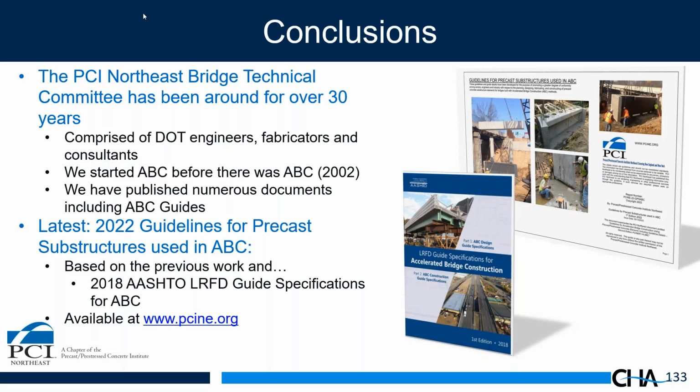Now, granted, this document was put together in 2018. There was limited research on seismic connections, but there was some research. So there are a handful of connections that are included that are seismic connections. The key thing is grouted couplers are difficult, especially when you're using displacement-based seismic design, because the couplers affect the geometry of the hinge when it forms. So a couple options are available. One is putting the grouting couplers in the footing. Other options include the pocket and socket connections that we described that are seismic connections as well.